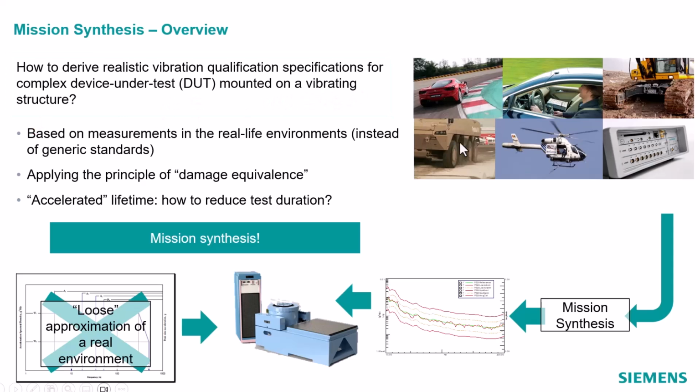All of these different components that we might design, we want to design them to meet a service life, and they may fail in the field due to a fatigue failure caused by vibration. So often the way that people will examine or test these articles is they'll use some sort of standardized PSD profile, and then they will shake that component on a shaker table using that standardized PSD profile.